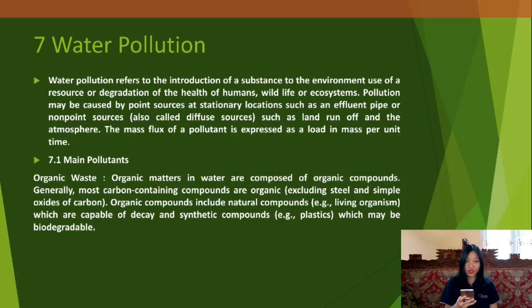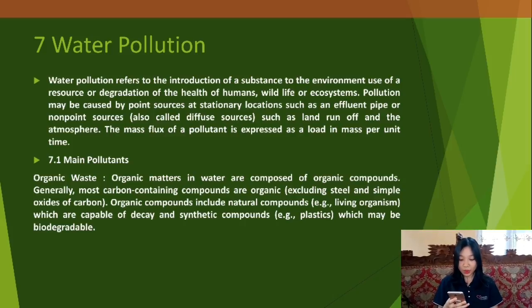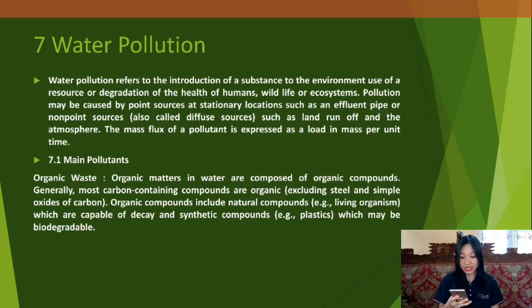Now I will present my group assignment with the title 7 Water Pollution. Water pollution refers to the introduction of a substance to the environment, use of a resource, or degradation of the health of humans, wildlife, or ecosystem. Pollution may be caused by point sources at stationary locations such as an effluent pipe, or non-point sources, also called diffuse sources, such as land runoff and the atmosphere. The mass flow of a pollutant is expressed as a load in mass per unit time.